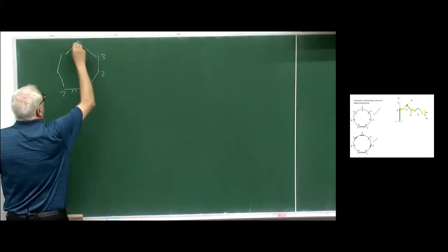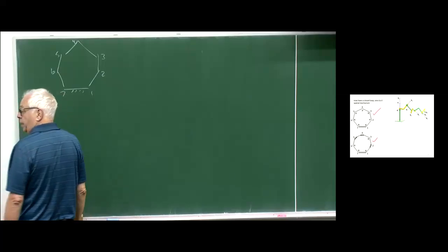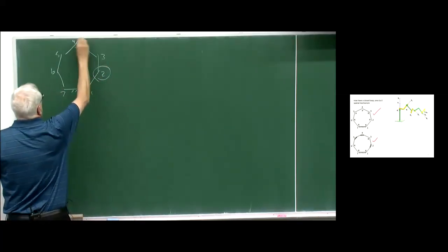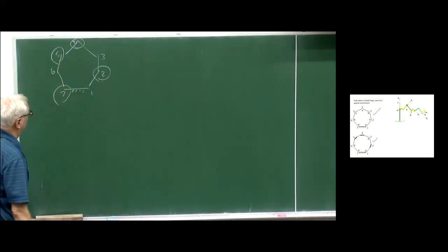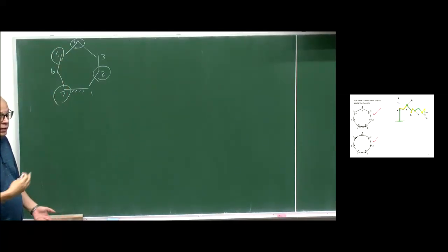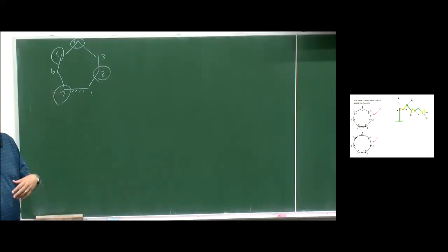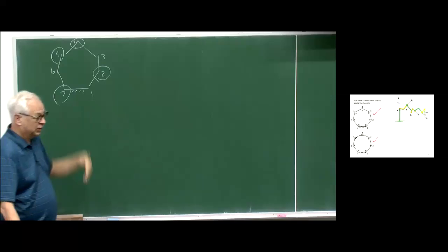1, 2, 3. And I'm going to say, what angles do we know? Let's see, there was a prismatic at 2, so I know that one. There's a prismatic at 4 and a prismatic at 5. I know theta 7 from close the loop. So again, whenever we analyze a group 1 mechanism, I say that solving for the joint angles is decoupled from solving for the 3 joint offsets. In other words, we're going to be able to solve the joint angles by looking at the equivalent spherical mechanism.